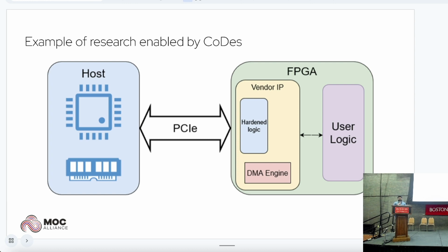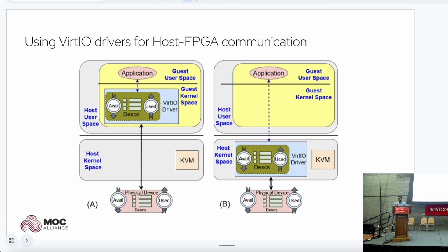However, if we can use standard in-kernel drivers like VirtIO, we can remove a lot of this overhead of maintaining these drivers. So what we did is implement a VirtIO-compliant interface on the FPGA itself, so that we can use unmodified VirtIO drivers to communicate with the FPGA.